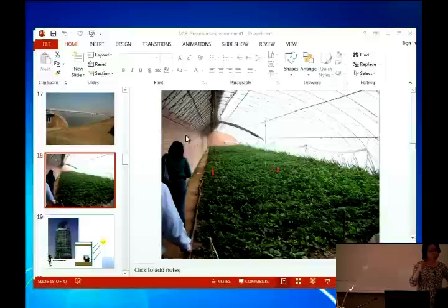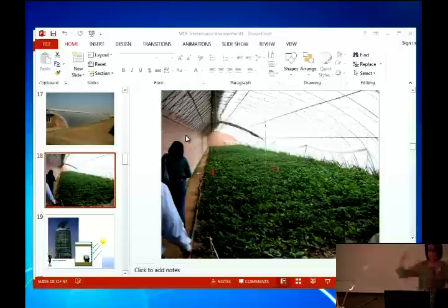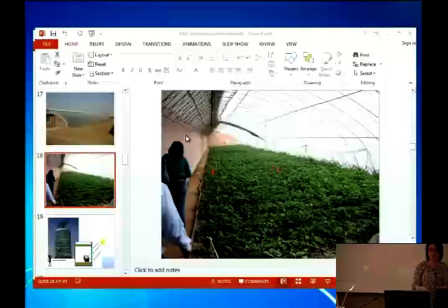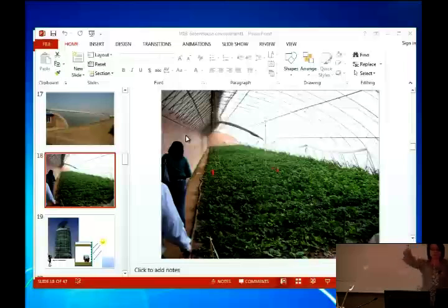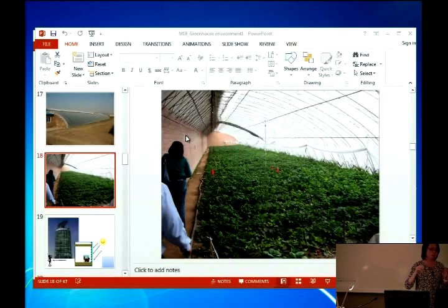Mirror works for direct radiation only. Okay? Diffuse radiation, basically the beams are everywhere, right? So the mirror doesn't quite reflect back to the direction you want. It bounces back, but it goes up, goes to the sideway, everywhere. So it may not be an effective way to either concentrate or redirect to a certain way.